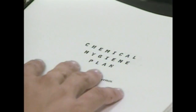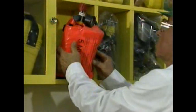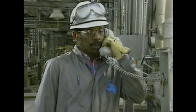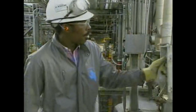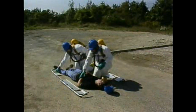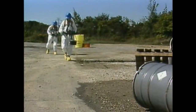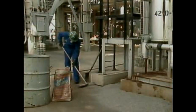It's important that you follow your company's emergency action plan in any situation, and you must know where your facility's escape respirators are stored in case a respirator is needed to safely exit an exposed area. After you've exited the exposed area, you should immediately notify the appropriate personnel. A specially trained crew may be required to rescue victims, pinpoint the source of the leak, and stop the leak. If the hazard is a spill, a specially trained crew may be needed to build a dike to control the flow of the spill, or to remove the chemical with an absorbent substance.